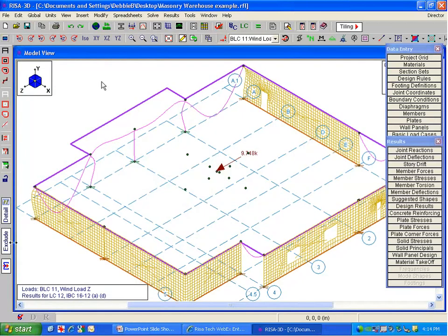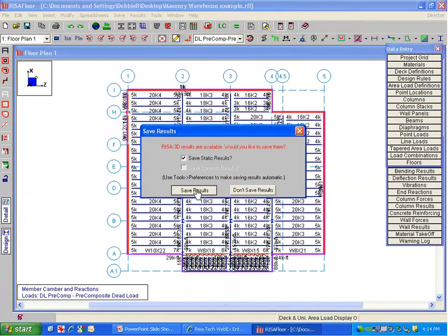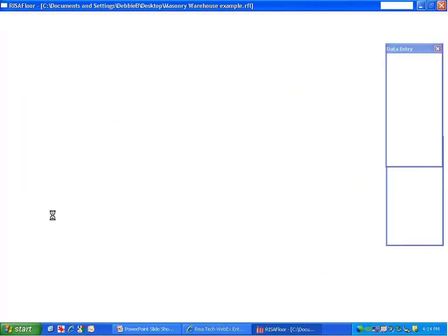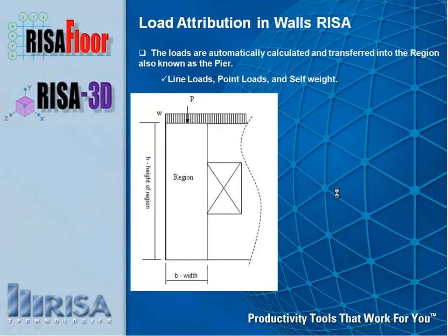So assuming that everything works out well here in the RISA 3D model, I can use my director button to go back to RISA Floor. I can save the model, and at this point maybe go into construction drawings by exporting it directly into DXF format, or I can send it into Revit Structure, or I can just start creating actual reports based on that.